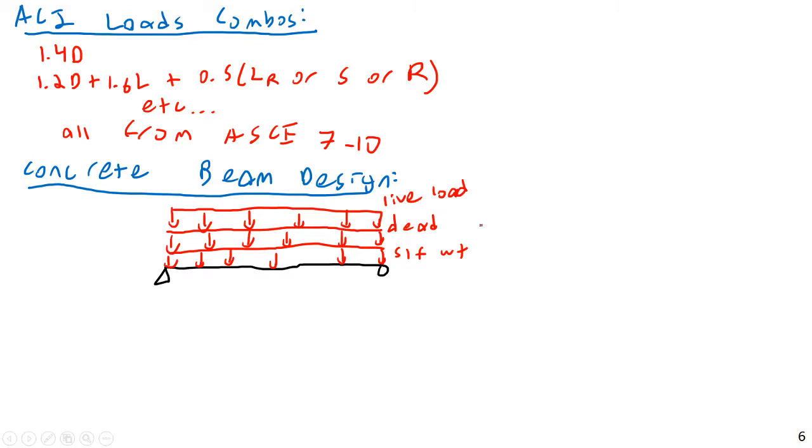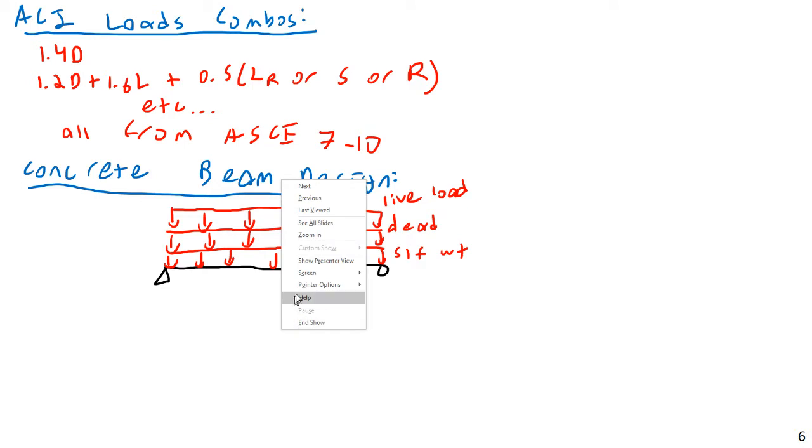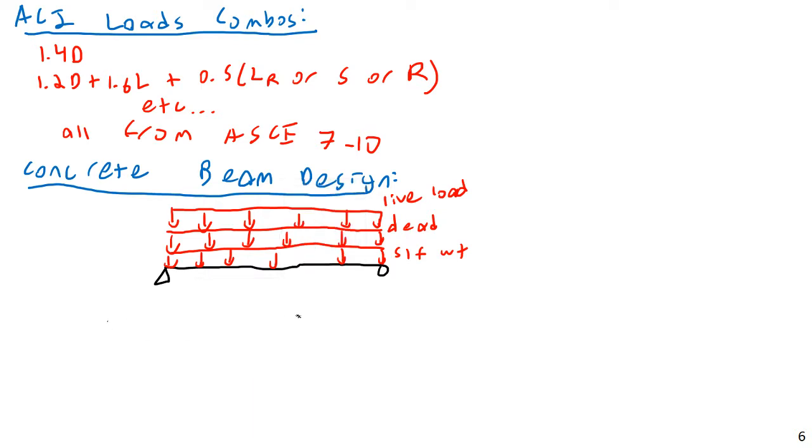However, we do realize that for a concrete beam, because it's going to have on average lower strength per unit weight, our self-weight component is going to be a bit more critical for concrete design than it is for steel design. Although, of course, for all beams, you need to consider it. Okay. We have different ways of approaching this. The difficulty with beam design is that, unlike with tension members, and truth be told, I kind of glossed over this in the tension member unit.